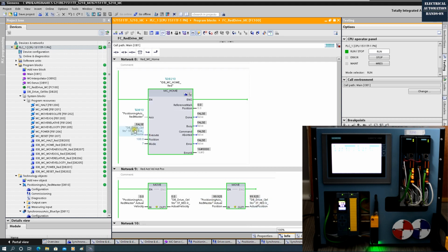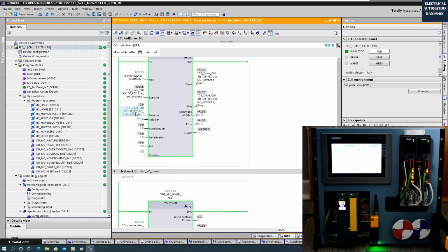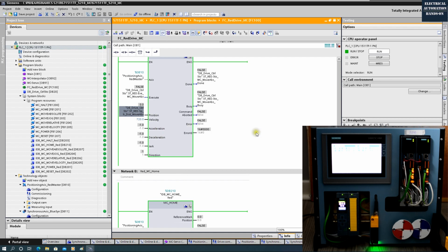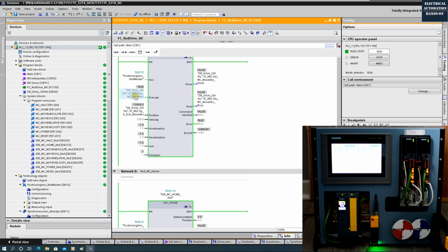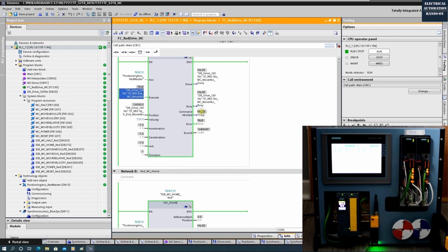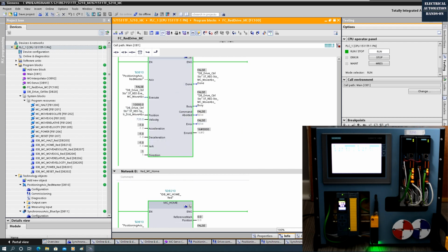Okay, so if now I travel to a position, let's travel to a further one, so 10,000, trigger. Oh, sorry, I forgot to power up the axis. If we forget to power up the axis, once I trigger, it will show the error. That's because after the power cycle, I haven't powered up the axis yet.